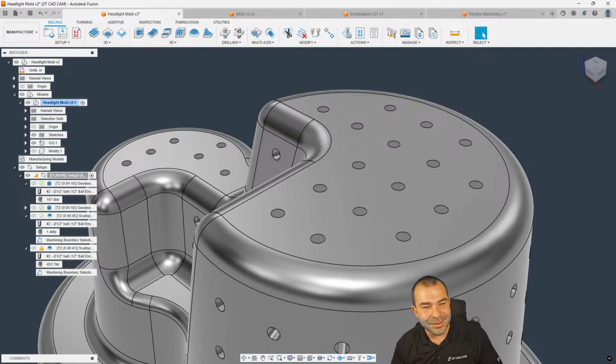My approach to zeroing a fourth axis trunnion. So, TC, I am actually doing a video on how to set it up, but the way I actually zero my fourth axis is I put a tooling ball in if I have a probe or a coaxial indicator, and I pick up multiple points across those arcs, right? So, more of a manual approach. Now, if you're dealing with a newer state-of-the-art machine and you have a probe, usually you're still using a tooling ball, and it's going to go through and do everything for you.